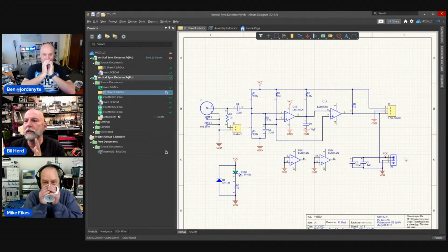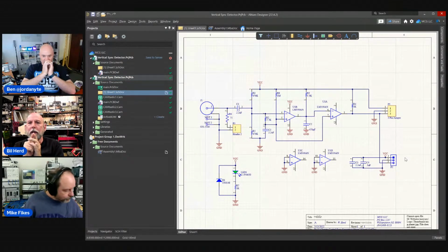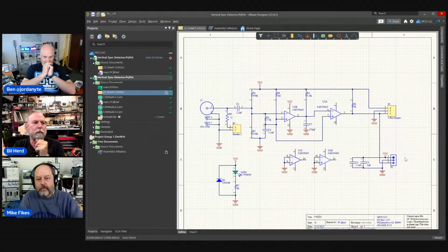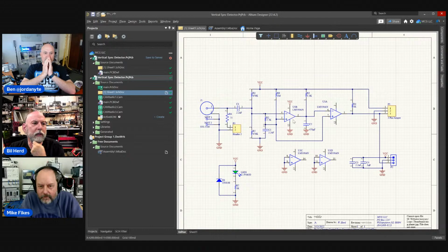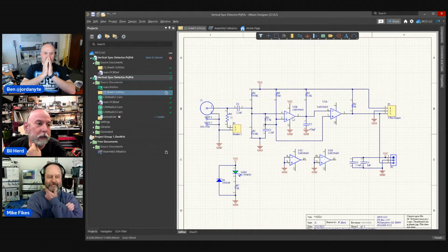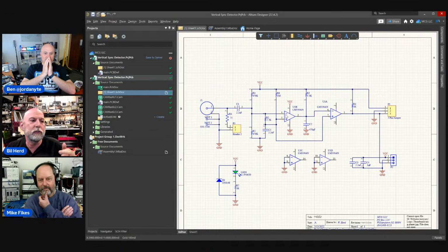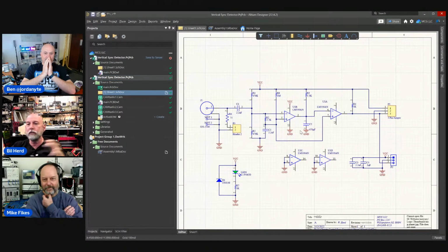Right. So there's one other interesting thing in here. Now I also need a pulse stretcher because that initial waveform was short. How do I make it into a long pulse? Well, the LM339 is an open collector comparator, and so I set the polarity. I could have made it high when true or low when true. I made it so that when I detect the signal, this grounds this capacitor. It does it very quickly because there's no R. It's just the output of the transistor.